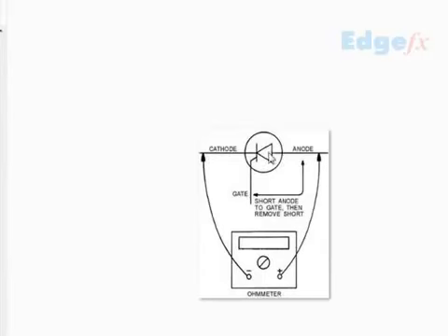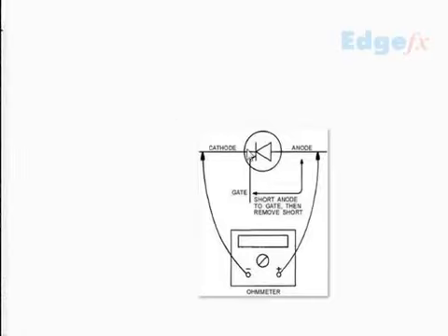In the process, this will continue to show conduction even if you remove the gate. Let me repeat it again. You have the connection like this. Connect the gate terminal with a wire or anything, or even with a resistance, just between here and here. So what happens? The gate gets triggered. Then remove this gate connection. They will behave like a diode.